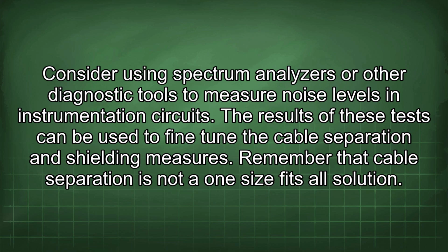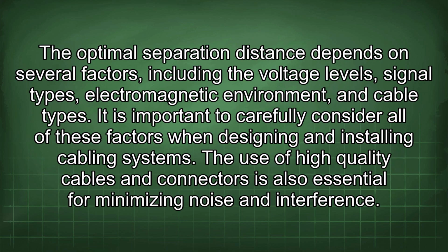Remember that cable separation is not a one-size-fits-all solution. The optimal separation distance depends on several factors, including the voltage levels, signal types, electromagnetic environment, and cable types. It is important to carefully consider all of these factors when designing and installing cabling systems.